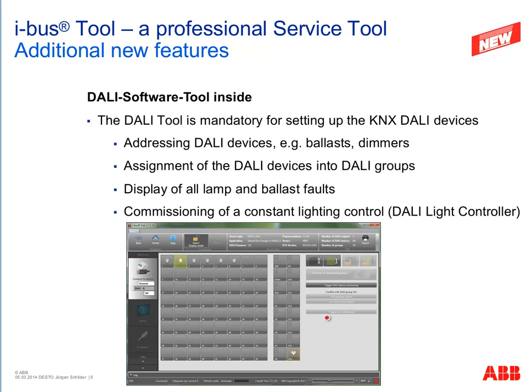So what is new inside this new IBUS tool? We have inside our so-called DALI tool software. This software ran up to now as a separate tool, but now we have integrated it into our IBUS tool. This DALI tool software is necessary for setting of our KNX DALI gateway and the DALI ballast. Via the DALI tool software we can readdress DALI devices, we can assign DALI devices into groups, or we can display lamp or ballast failures, and it helps us for the commissioning of our constant light system, for example via the DALI light controller.